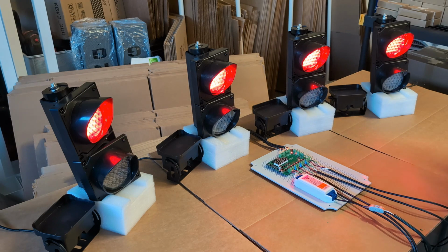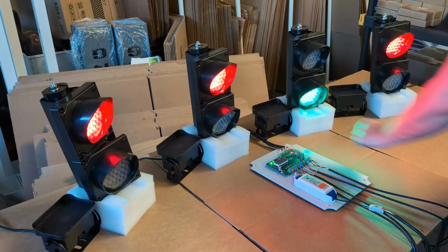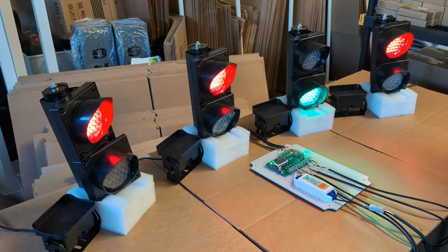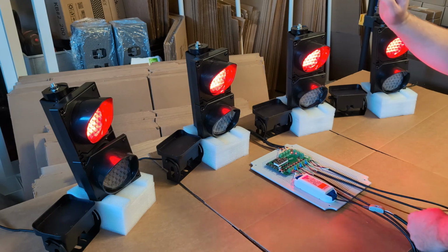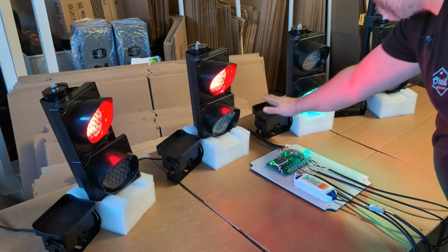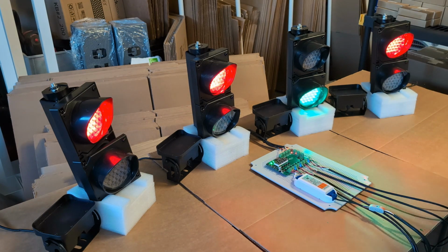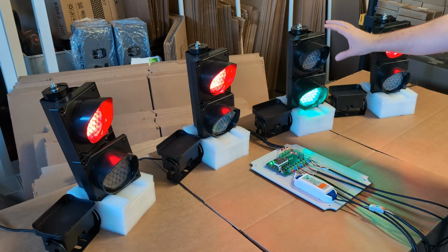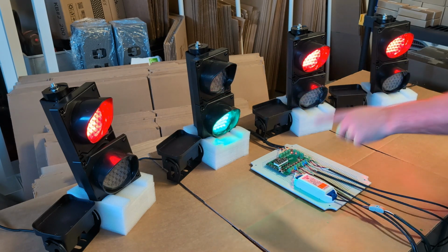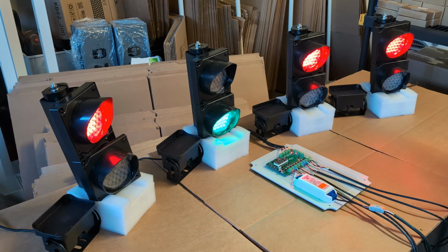However, let's do this where a vehicle is detected on sensor 3, and then another car right after the first vehicle. This starts the activation timer over. This is designed to avoid a secondary green light to activate when a vehicle is still in the intersection. So I activate here, I activate the second one, I activate this. This will continue to allow the operations to stay on this light, and then eventually when traffic is clear from this lane, it will go to the second lane.